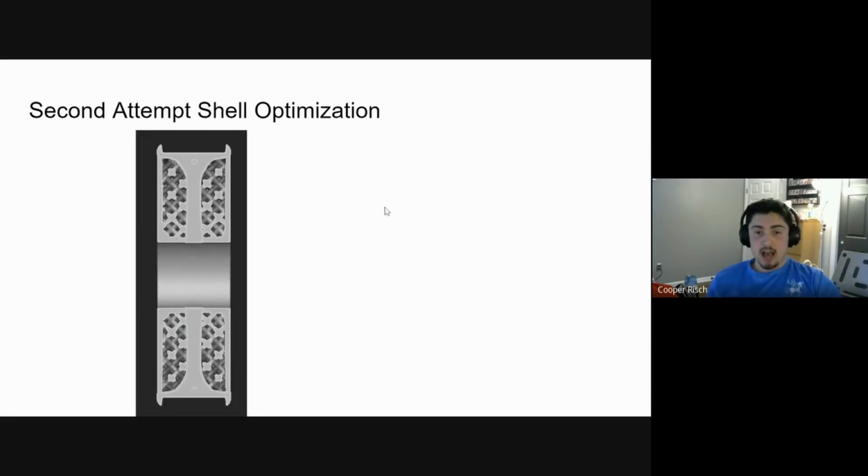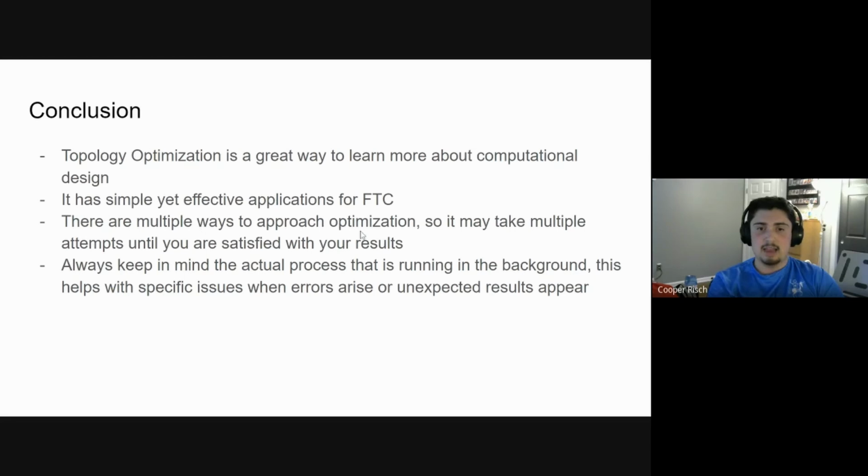And then again with the shell, as we look, and I talked about the bone earlier, we need something to surround this mesh to hold it together. And so we can use a shell that is also driven by thickness or driven by stress to change the thickness. So in areas of lower stress, it's thinner, and in areas of higher stress, it's thicker. And this is all done with computer. I don't have to do any manual calculation. I have to know what the computer's doing, but I can just tell it to drive it, and it helps us end up with this optimal solution.